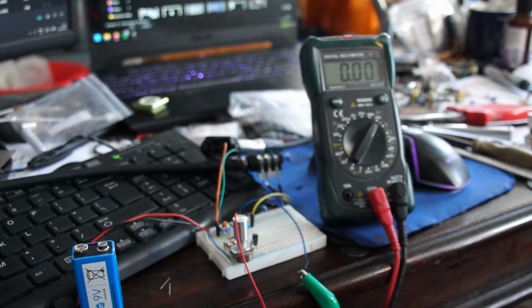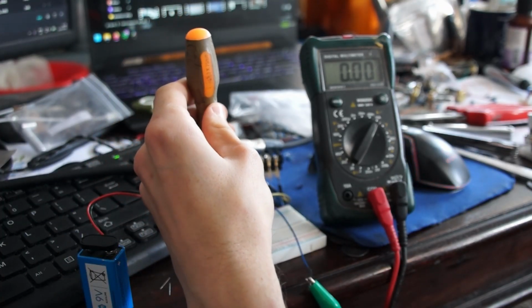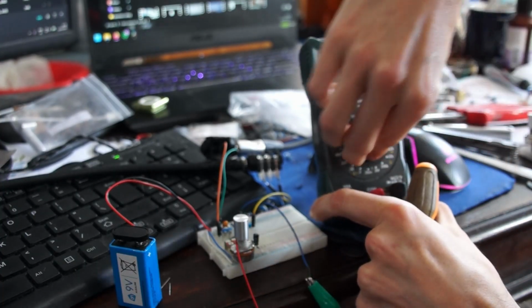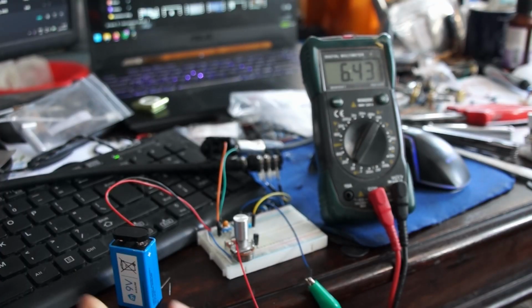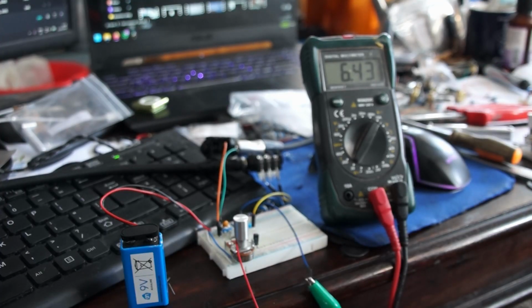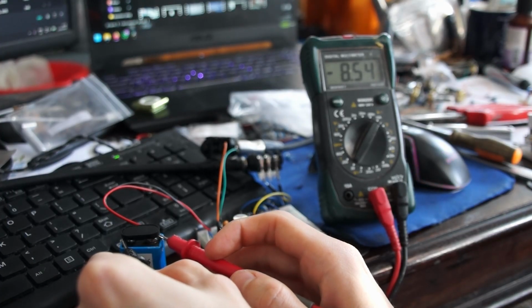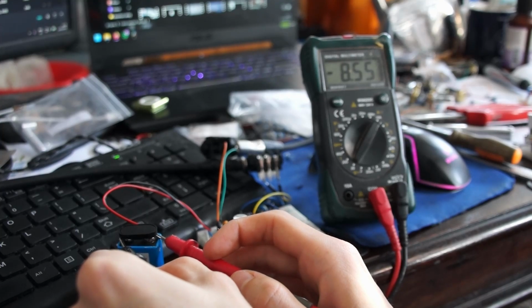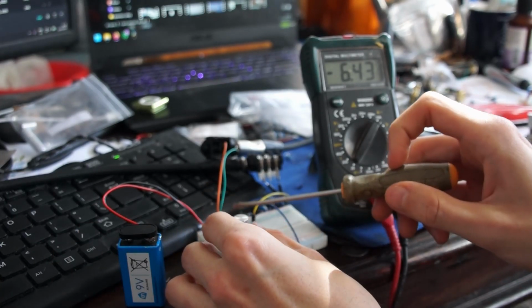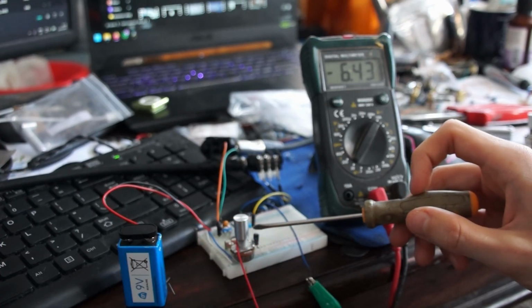Okay, so I just assembled the prototype. And remember how we had to tune the bias? Oh, I put it on 10 amperes instead of 20 volts. Stupid of me. Remember, since this is assumedly a 9-volt battery, let's actually first check the battery voltage. So checking the battery voltage while it's working, it's 8.55, and we want to bias our transistor in the middle of that. So that's going to be 4.27.